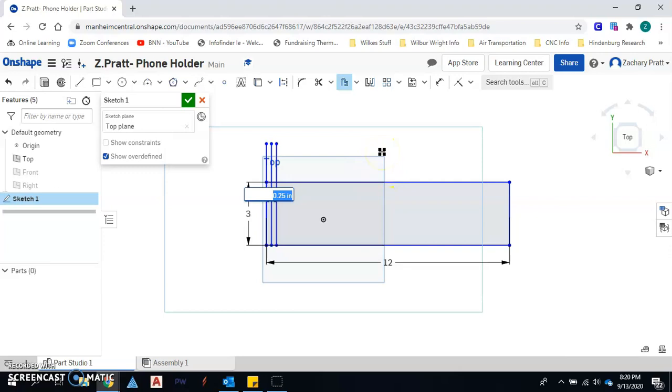And this one, I know that I have about 5 inches to work with. So I'm going to hit enter. And so this is like the front side or the front panel of my phone holder. I'm going to offset from this bend now 4 inches. And again, you have to hit enter to lock in that you're offsetting that direction. And I'm going to type in 4 for my measurement. Again, this is always going to be in inches, and hit enter.